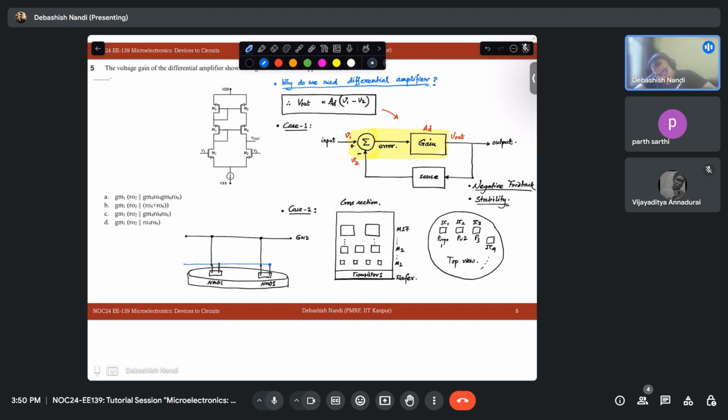You will have a metal layer coming here. Let's say this is your M1 dedicated for this NMOS 2, and this is connecting to your, let's say, M5. Okay. Metal layer 5. So in ICs, there are multiple transistors, and all the transistors for all the purposes will have to have different types of voltages. So if you supply all the contacts through the same metal line, it will get shorted, it will not work. So you need to have multiple metal lines crossing on top of your transistors. So how will you cross those metal lines?